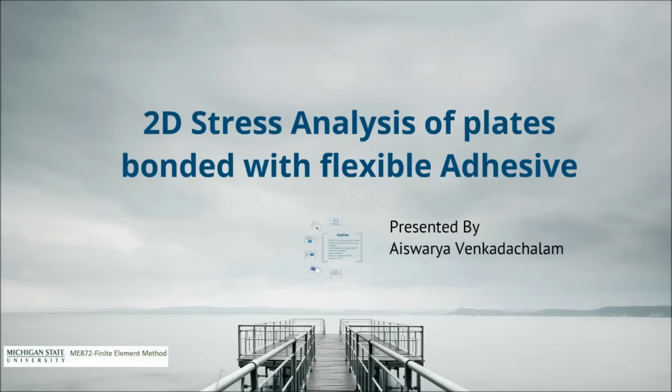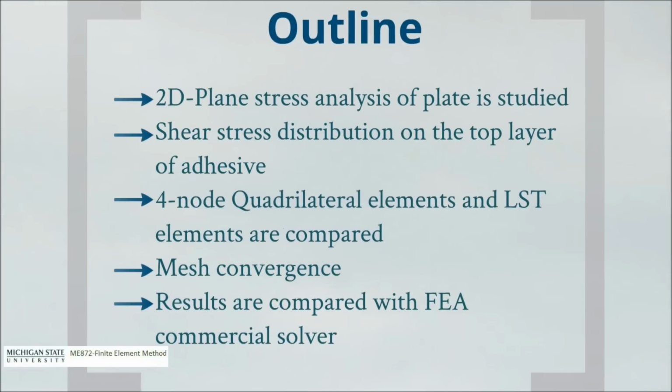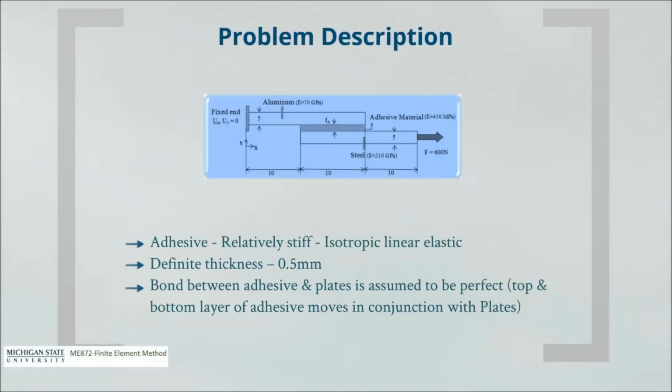I will be presenting on two-dimensional stress analysis of plates bonded with flexible adhesive. Here is the brief introduction about the project. 2D plane stress analysis of the plate is studied in scope of finding shear stress distribution on top layer of adhesive. Stresses are compared for 4-node quad element and LST element. Mesh convergence is performed by H refinement method. Also, results are compared with ANSYS results.